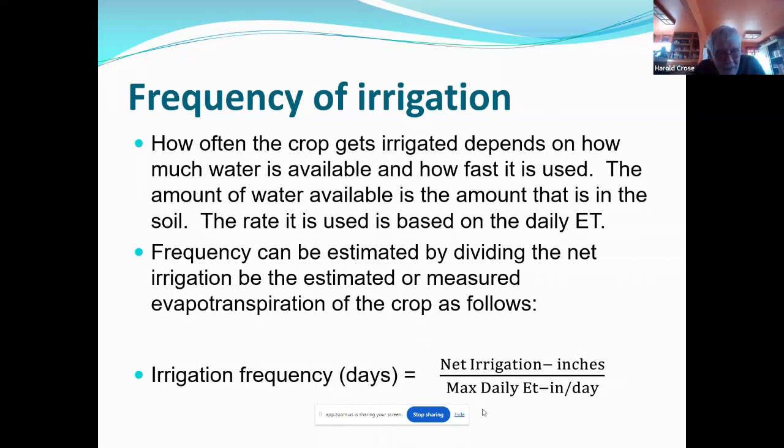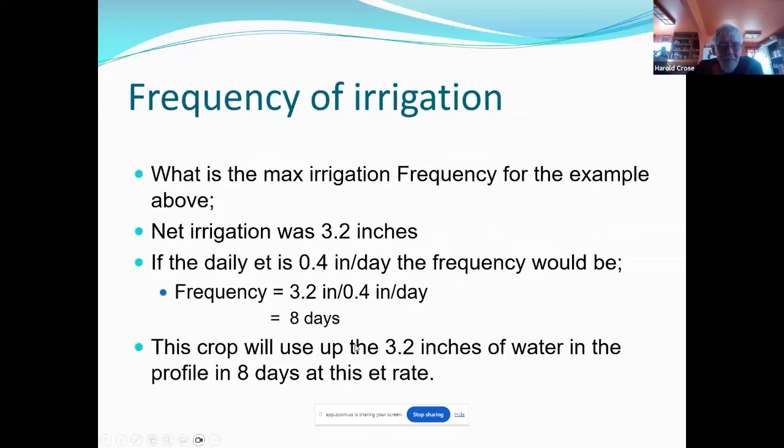If they go to the end on that fourth day, and then rather than take the time to take that system all the way back up to the beginning of the field where they started, they start irrigating from the bottom back up, they'll over irrigate and under irrigate the top part of that field, if it makes sense. You've got to take those hand lines and wheel lines back to the starting point and start irrigating again. Don't just irrigate in reverse back up the field. That seems like a simple concept, but I see it all the time because it's labor. It takes labor to do that, but it's well worth your time.